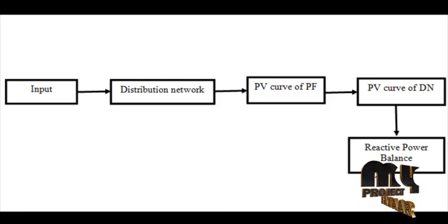KQP equal to 0.2, 0.4, 0.6, 0.8 are the various ratios of reactive power with respect to active power for the grid reactive power voltage characteristic, and these curves are drawn with the load reactive power voltage characteristic. There are two cross points between the load reactive power voltage characteristic and each grid reactive power voltage characteristic.